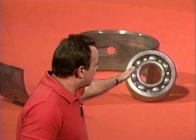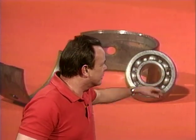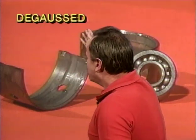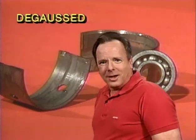Well, yeah, it's a bad deal because it's going to attract every iron filing that's around, and that is a bad deal. You don't want to attract iron filings in your bearings. So what should be done? Well, that bearing should be degaussed. That means you've gotten rid of the magnetism.